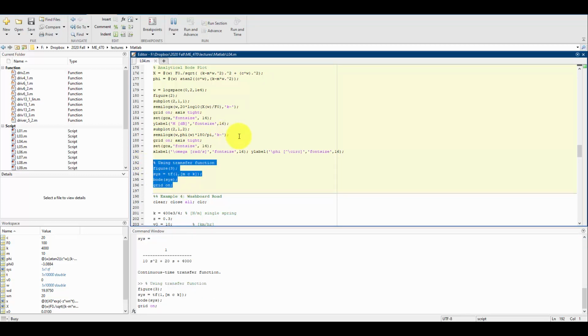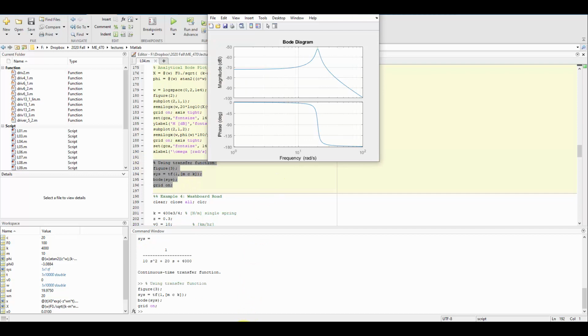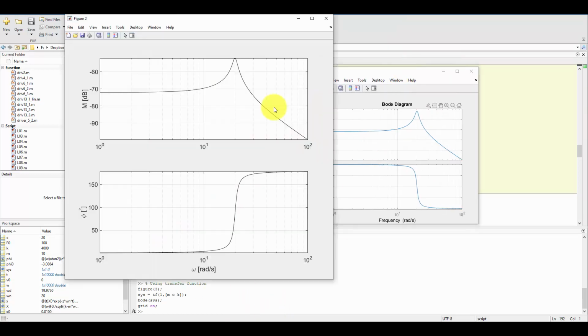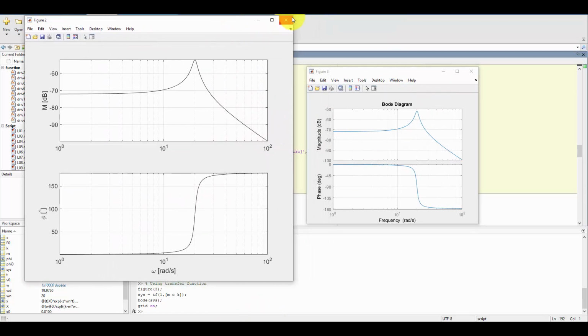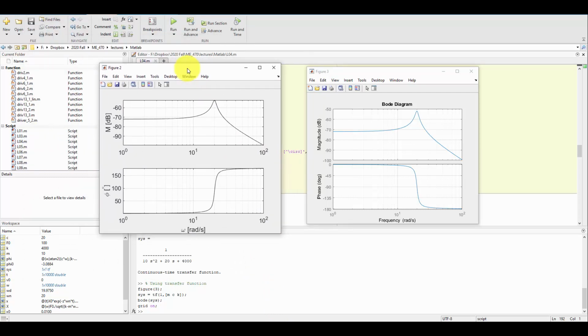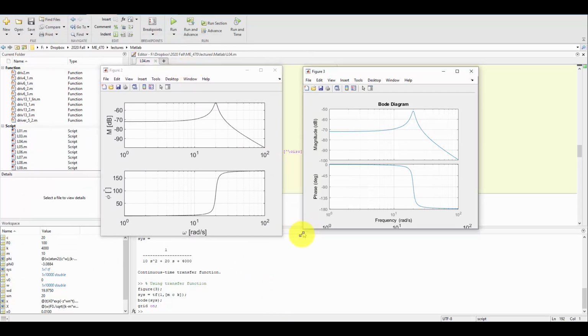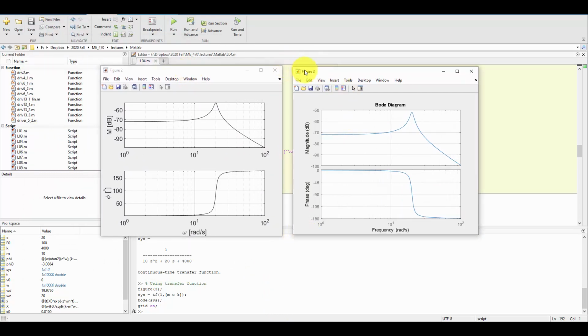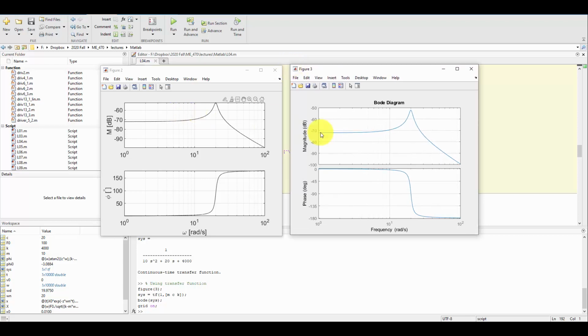So this will be another figure, so we can compare what we got doing it with a manual method to what we get using Bode in MATLAB. I'll put them side by side here for comparison. All right, so if we look at the magnitudes, we are seeing a pretty much flat line, a little bit less than -70 decibels, and then it starts to rise up.